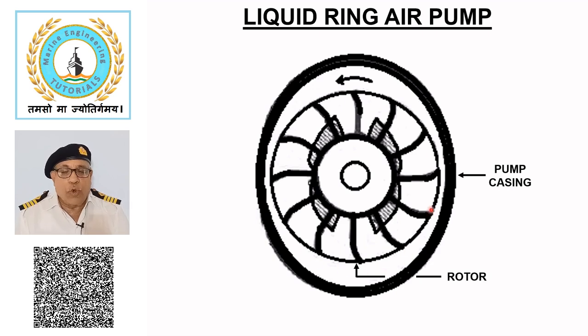The rotating rotor throws water to the periphery of casing where it forms a revolving liquid ring along the oval inner surface. This liquid ring seals the rotor blades and alternately recedes from and reapproaches the rotor hub twice during each revolution. Its effect is to form a series of reciprocating water pistons between the blades.